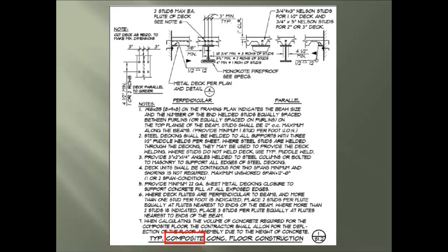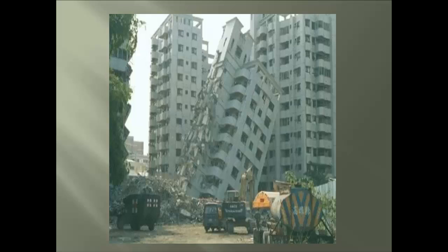It is when you take items such as headed studs, steel beams and columns, concrete, reinforcing steel, fireproofing, and metal decking, all acting as one to allow the forces that are introduced during an earthquake to move through the structure and disperse out through the soil, so we don't have a disaster.